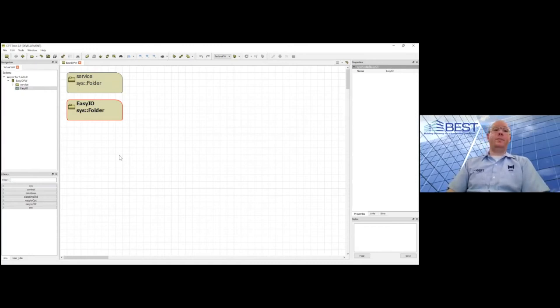So we will probably run into more things that'll crop up later on. But for right now, let's come over to our library and we're going to open our control folder. Oh, I should point out the libraries currently showing up in this library are the libraries installed on the controller. There is nothing in here that you cannot use. There are some things you should not use, like things out of the EasyIO CPT folder, for example.